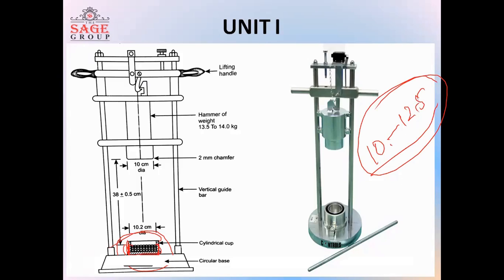It is filled in 3 layers. After filling each layer, tamping is done by the tamping rod 25 times.